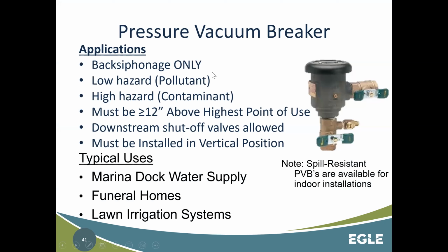They are back siphonage only. They are used for low hazard and high hazard both, okay? They can be used for high hazard because if they're on lawn irrigation systems, as long as the pump is not downstream from it, even if they have chemical additives, they are allowed because it's a high hazard application. You see these in marinas too and funeral homes, but lawn irrigation systems are the king of where you see these, just FYI, okay?